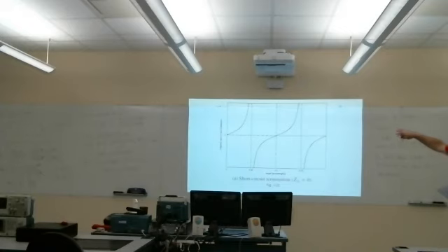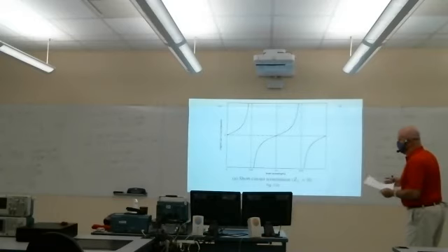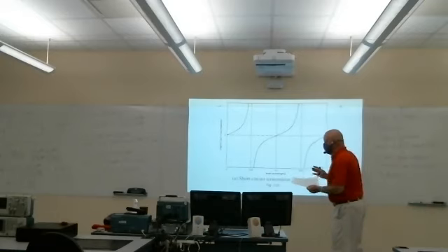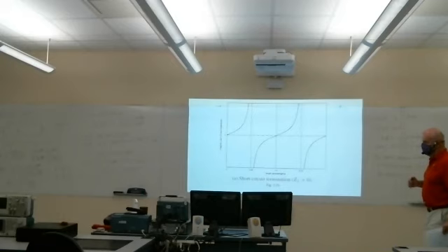And we'll see applications of that, I believe, next lecture. And an open termination can be used similarly. Here with the short circuit, during the smallest segment, you actually get an inductive impedance. With the open circuit, during the shortest segment, that first quarter wavelength, that looks capacitive. But you can use either.